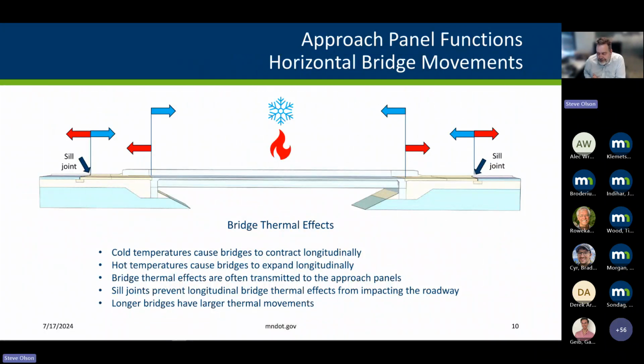We're going to get a little more nuanced here. Our bridges expand and contract with temperature changes, and oftentimes it's roughly an inch per 100 feet per temperature range we need to worry about with bridges. It gets a little tricky with how the bridge abutments are configured and how that movement gets considered, but the roadway designers should not need to worry about it too much.